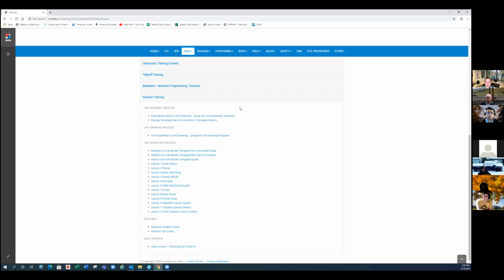We initially tried to really lean on STEP file creation so that the shop could just use that with the CAM Plus software, because it's supposed to be able to recognize 3D notches and things like that, but it's not consistent. So for now, we have to go back to just using fab drawings.